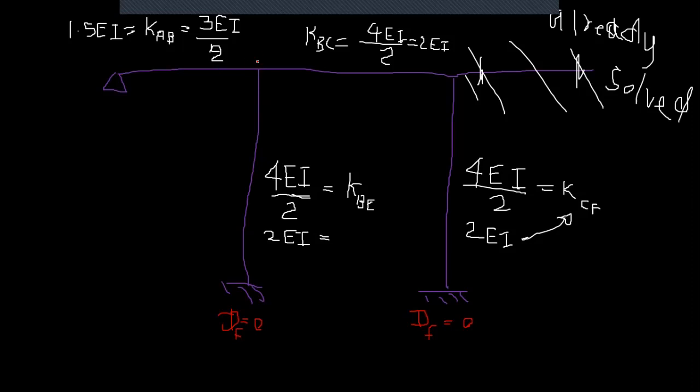So here if you apply bending moment, this will take some amount, this will take some amount, this will take some amount. That amount is equal to the distribution factor, right? Here you don't need to worry because this part is already solved. The important fact here is we only consider these two members because the cantilever part is already solved.